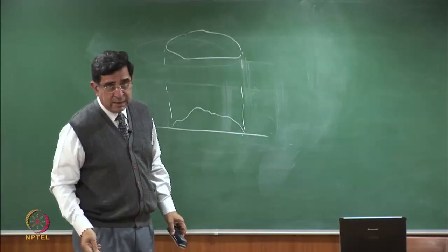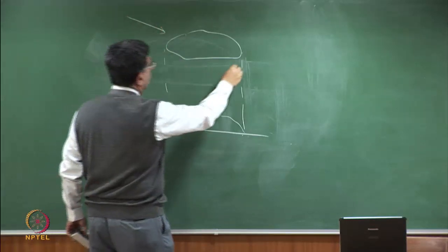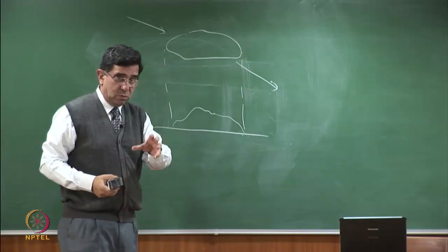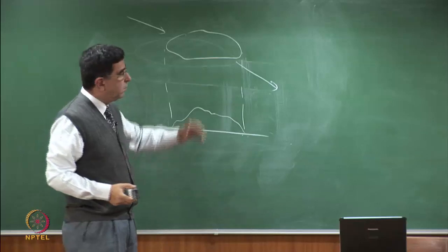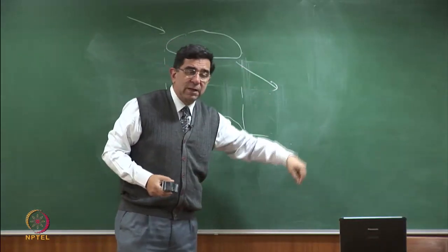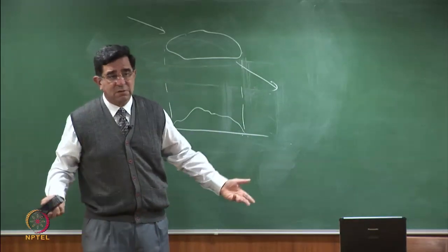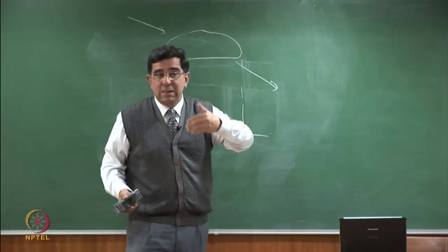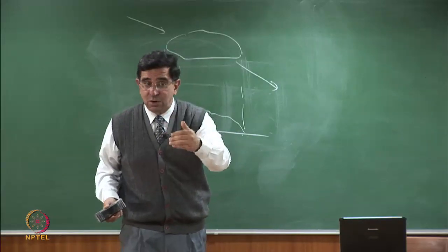I also know from my site investigations that groundwater flows like that. So I do know where the source is, but I don't know where to put my wells, because if the contamination has traveled, there's no point putting the monitoring well inside where the contamination has traveled. All that it will tell you is it is contaminated. After that, it will serve no purpose. If you put it outside the boundary, then you can tell whether the contamination has reached or not reached.